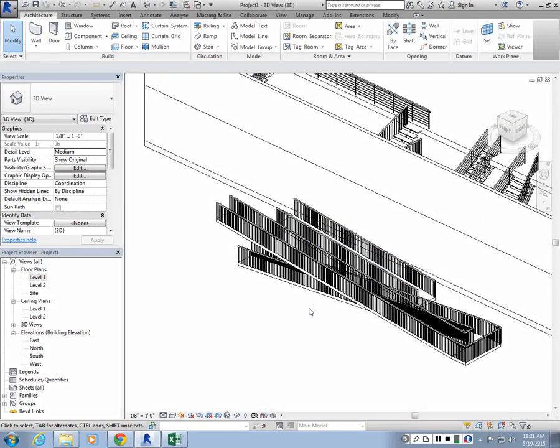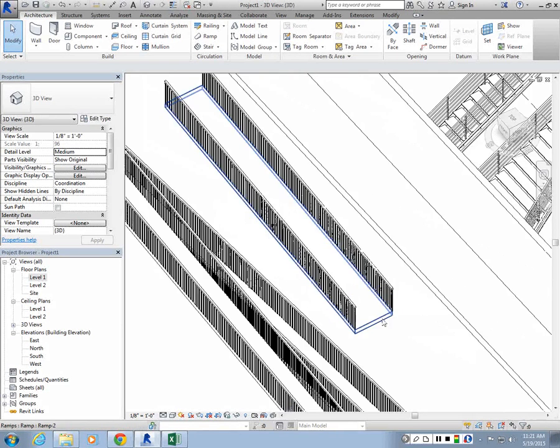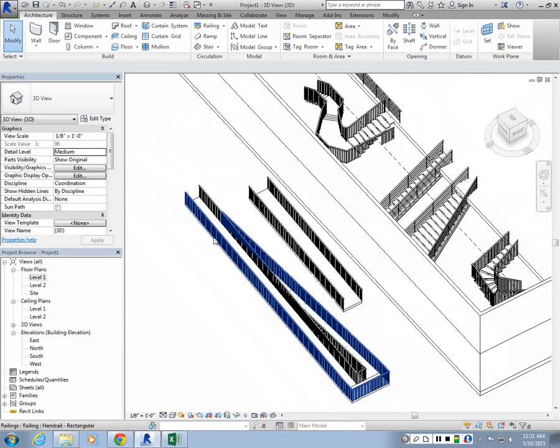Because I override the slope as well as the maximum run. Otherwise, what you have to do is calculate how much ramp length you need, and then create landings at each interval. I mean, there are some probably standards and rules for this, but for your projects, you can do something like this. Okay? Something really simple. That's basically it.